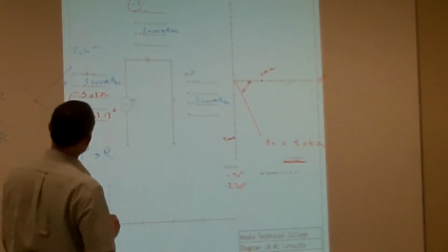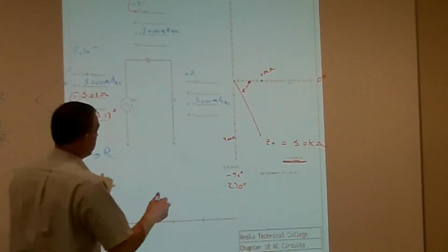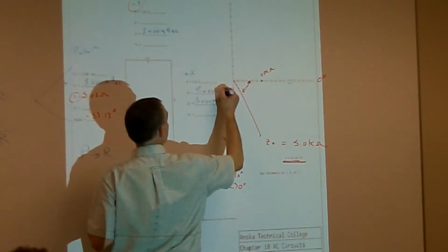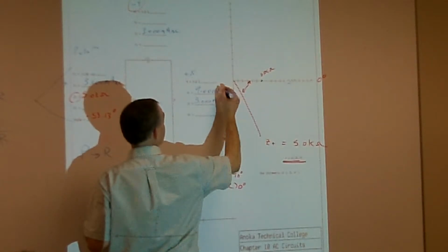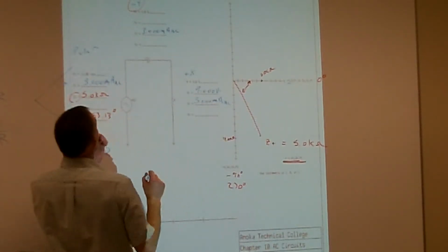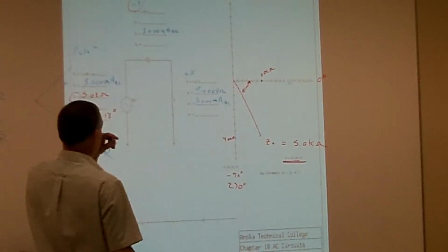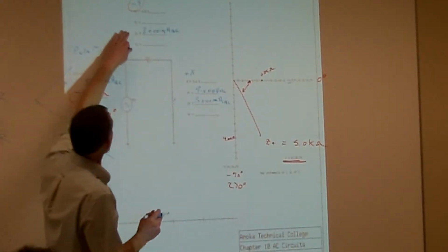And that's going to be my voltage of R. So VR is going to be equal to 9 volts, and what's your units? Volts AC, yep. Don't forget that. Okay? Then if I hit my second XY again on my calculator, I'm going to get my value of my capacitor.